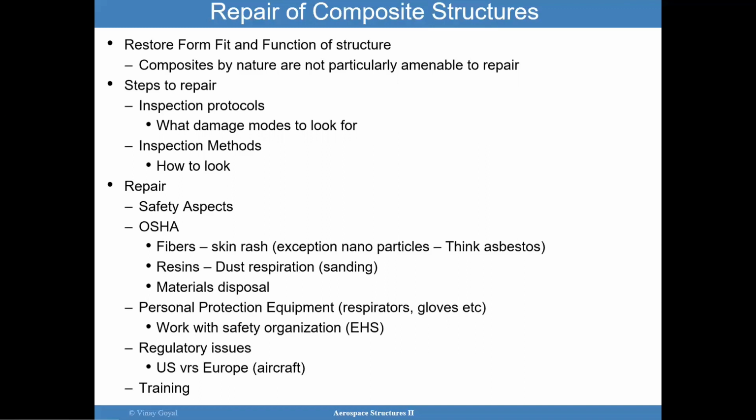And so this next thing we want to look at is the repairs. You have repairs which require safety aspects, making sure you don't have any concerns with health issues. The fibers can cause skin rash, there can be asbestos particles, resin, and during the sanding process there could be dust that you inhale, and then there's materials disposal. Personal protection equipment is important, and for aircraft you also have regulations.